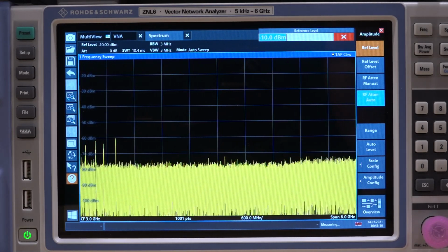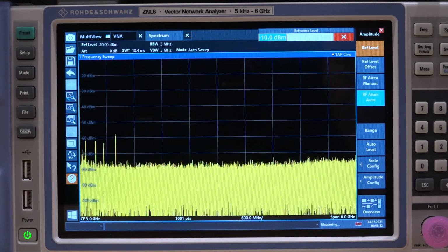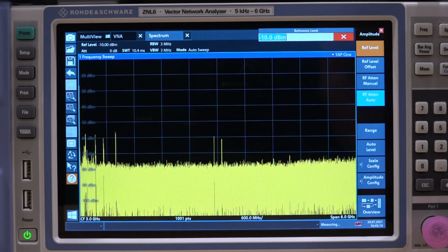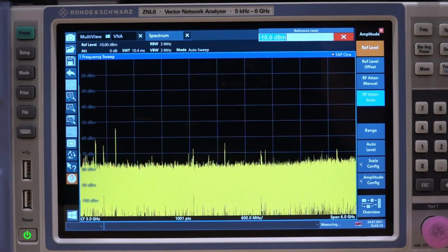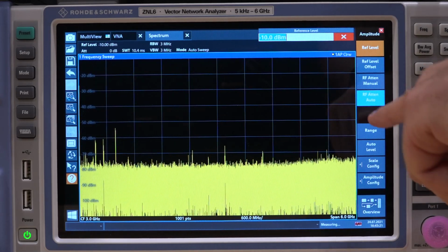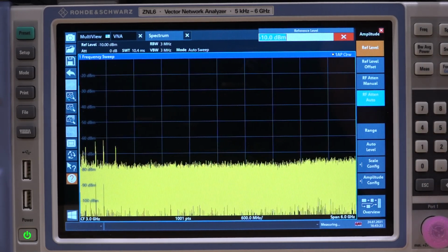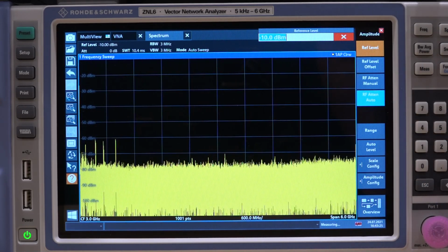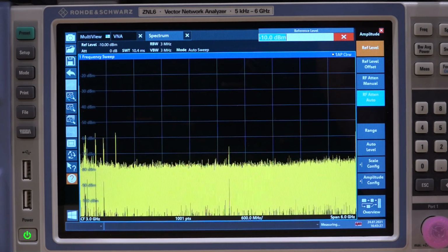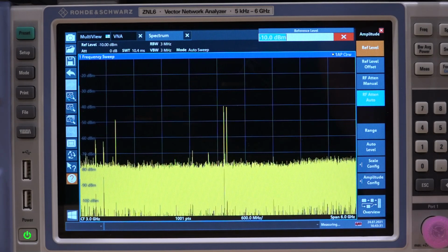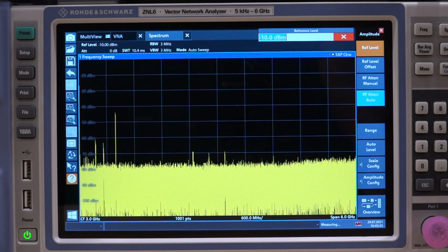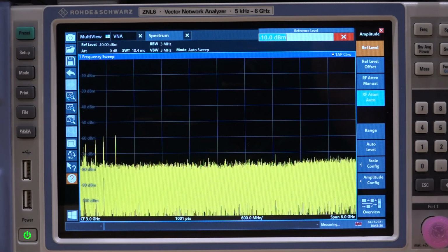Now we can follow that signal a little bit further down to see if it makes it past the first attenuator here. Let's see if it gets past that. There it is. Yeah, still present. Good. You can see some second harmonic over there too. Let's go to the input of the divide by 4, which I think is here. There we go. It's still there. Looks good.